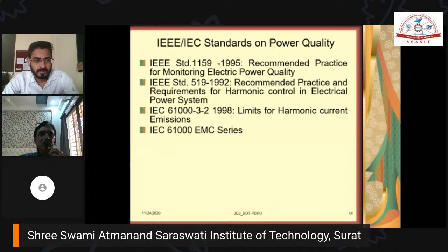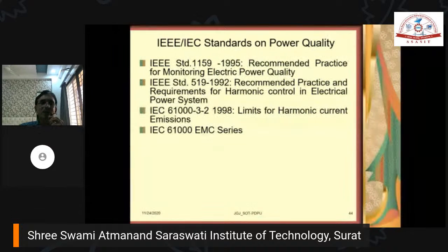Again, you have to remember the title. Many people just say "as per IEEE," but they don't remember the IEEE number, right? So as per IEEE 1159, what is the title? Recommended practice for monitoring electric power quality. It's a general standard, and particularly for harmonic control, we have to refer to 519.